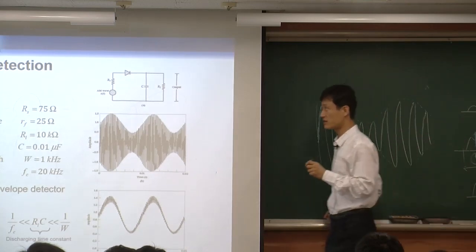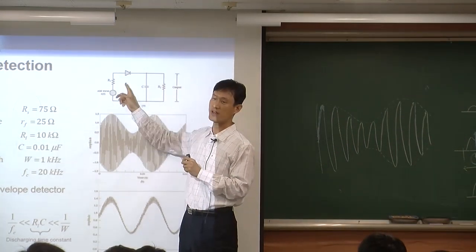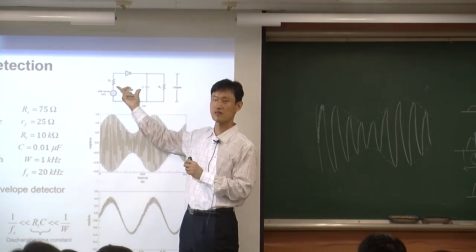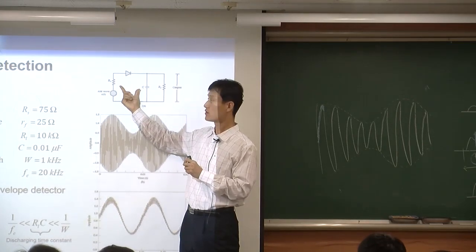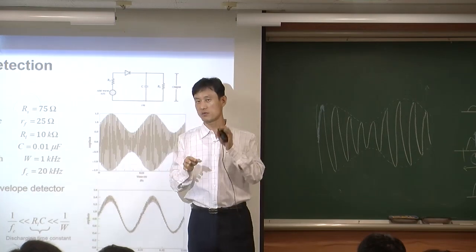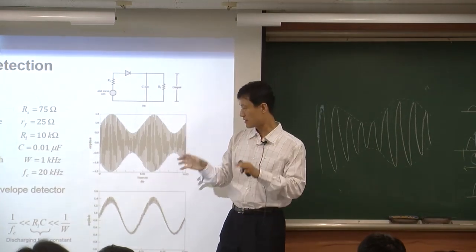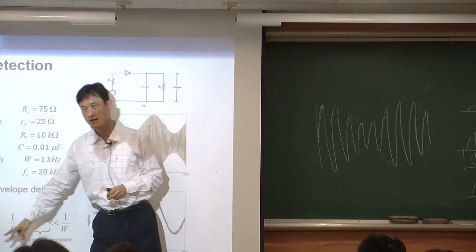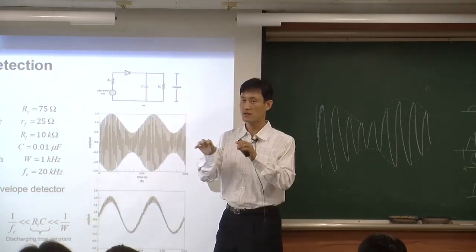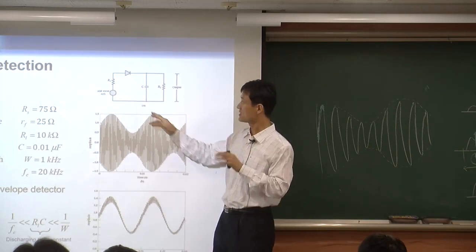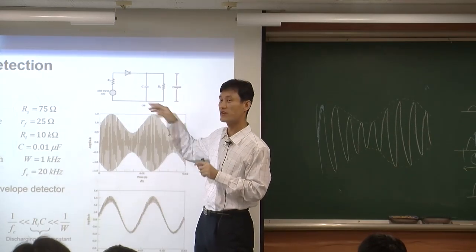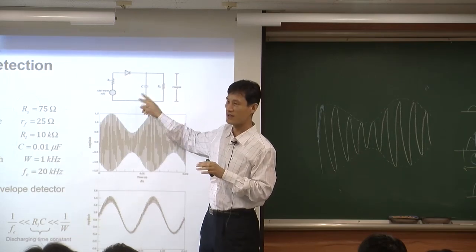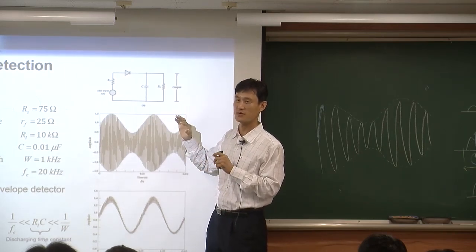So the idea here is that you want to charge it very fast. When you charge, you're going to use the RC circuit. Using this RC, when you multiply R and C, you can calculate a constant, right? Based on this R and C, you can design it so that you charge very fast and discharge very slow.